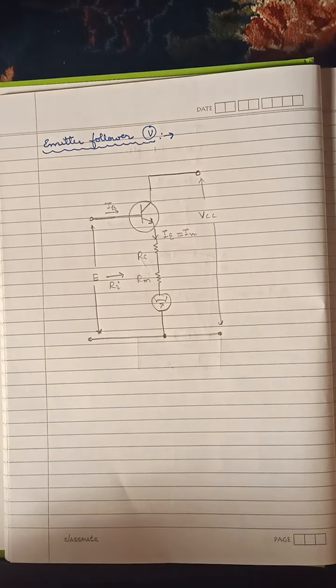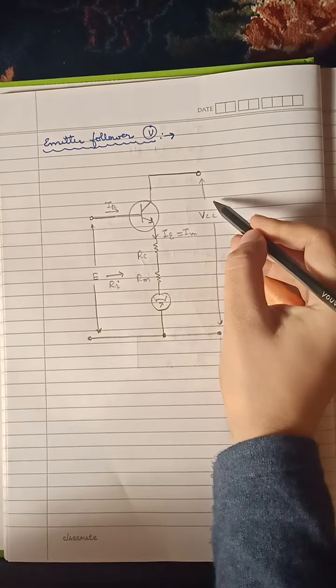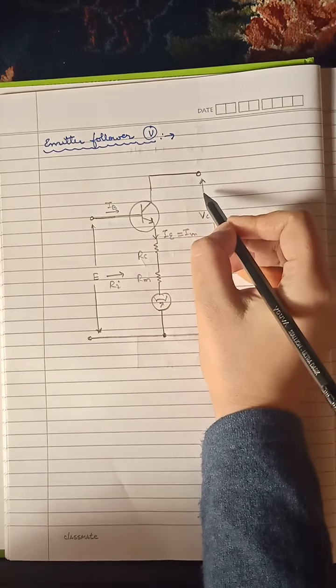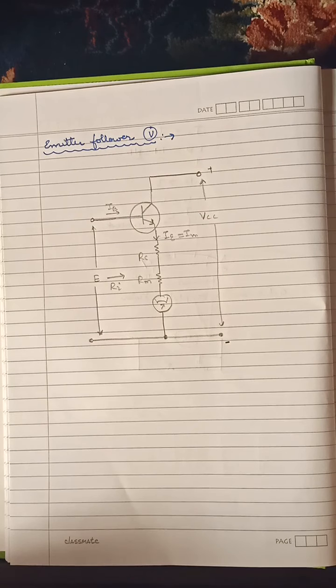Now how do we say that this is an electronic voltmeter? So in this case, how do we justify that? VCC is basically the supply voltage you provide between the collector and the emitter side. Voltmeter loading is greatly reduced by using this emitter follower configuration. An emitter follower offers a high input resistance to voltages being measured and provides a very low output resistance to drive the current through the coil of the deflection meter.